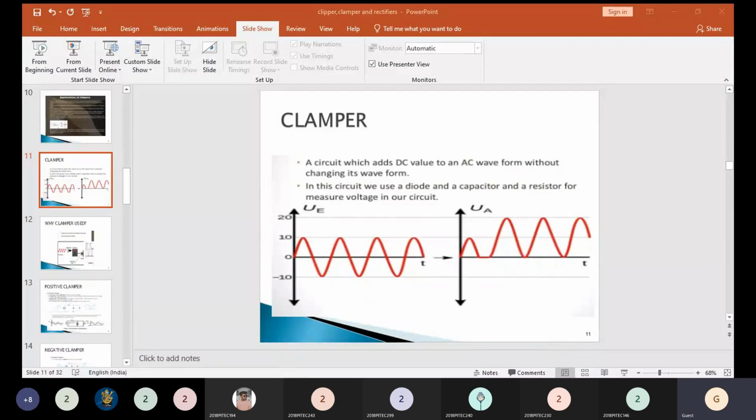Wrongly you will compare. That's why I'm telling you, while writing the m value, whether it is milli, micro or nano, be careful in that area. Okay, so 0.001, or you can also write 1 into 10 power minus 3, divided by 25 into 100, that is 0.004 percent. So which one is better? Clearly power supply B is better.